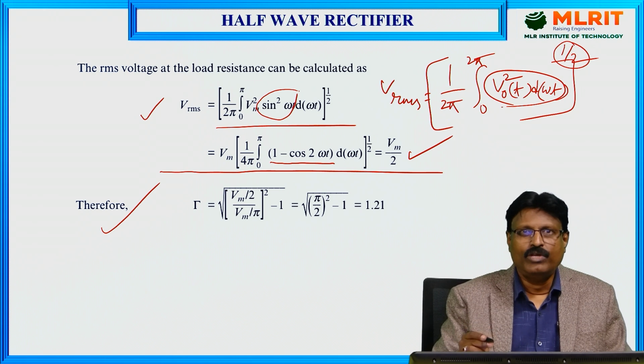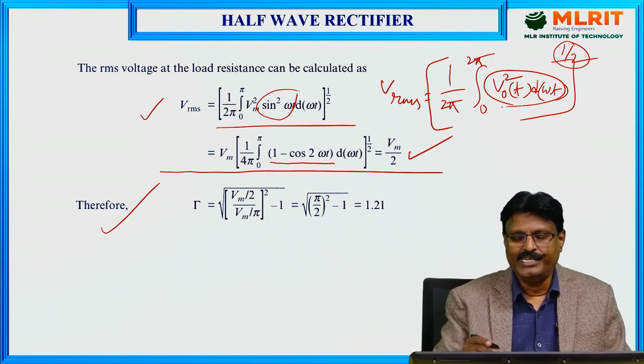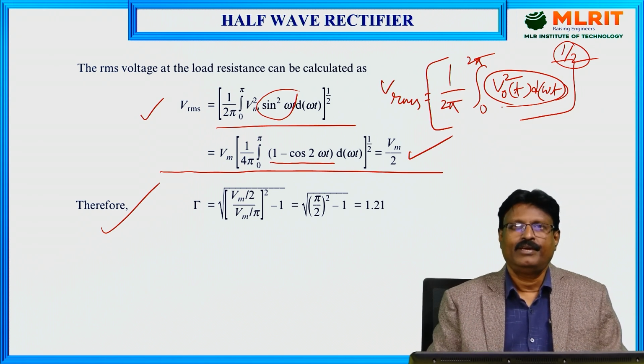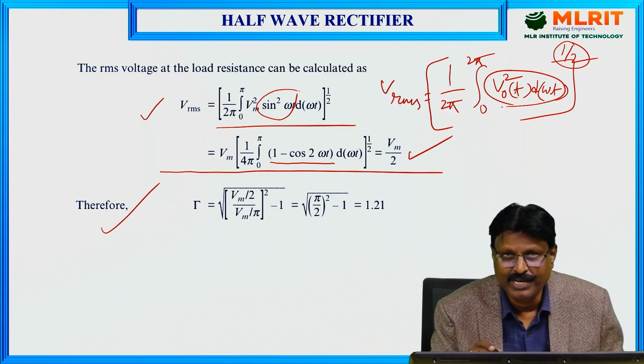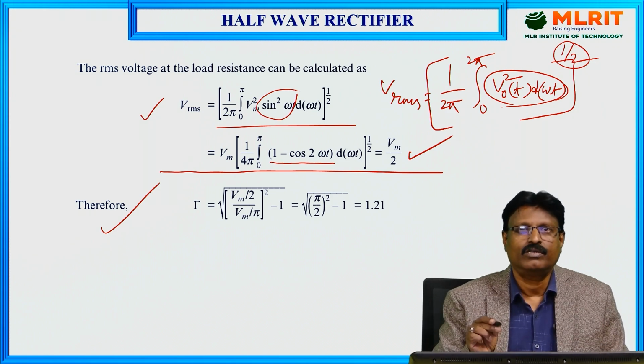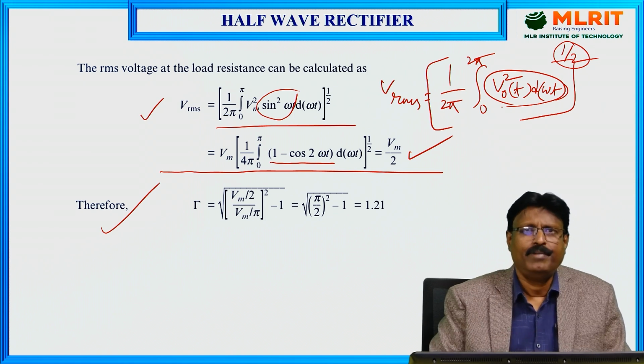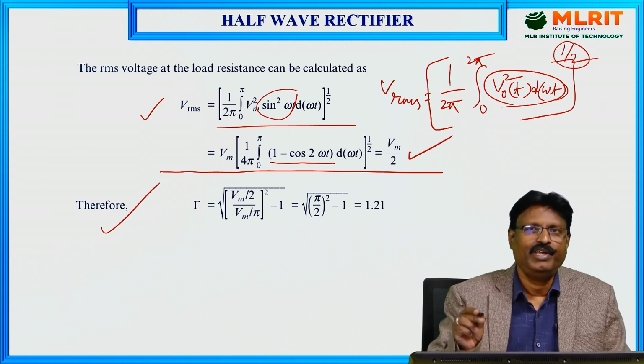If you know the value of ripple factor, you can judge the performance of the rectifier. Whenever it is very, very high, we can say that the rectification is not good. It is a poor one. So that's why it is an important parameter we need to calculate for each and every rectifier.